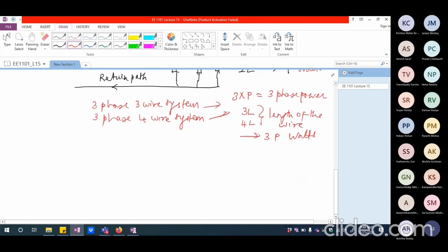So you imagine that, let's say I'm going to have my machine like this. So I have to probably have A-phase conductors here and A-phase return conductors here. Then I might have to have B-phase, C-phase conductors, return conductors here, and again C-phase return conductors here. Then I might have to have B-phase here and B-phase here too. So I can call this as A, maybe A dash. I can call this as B, this as B dash, and I can call this as C and C dash. This is the way the conductors are distributed.